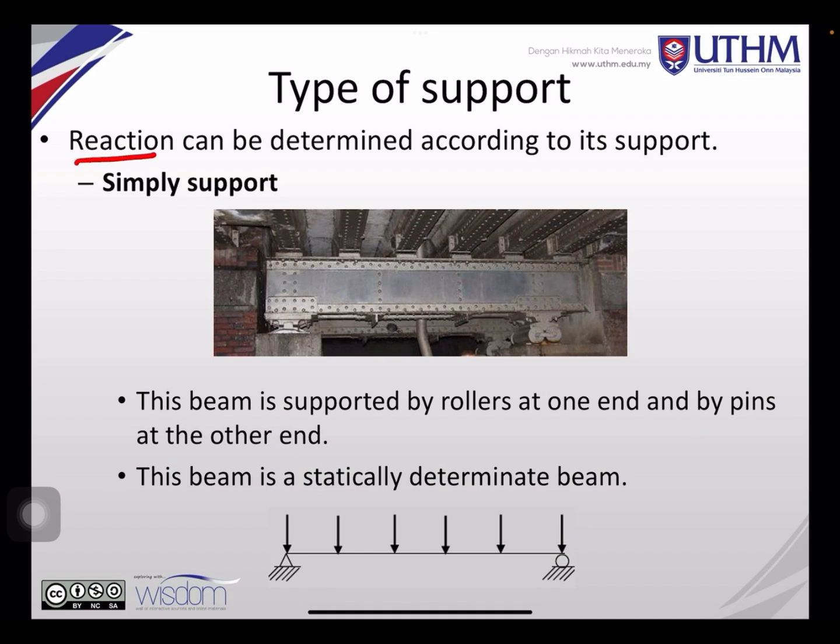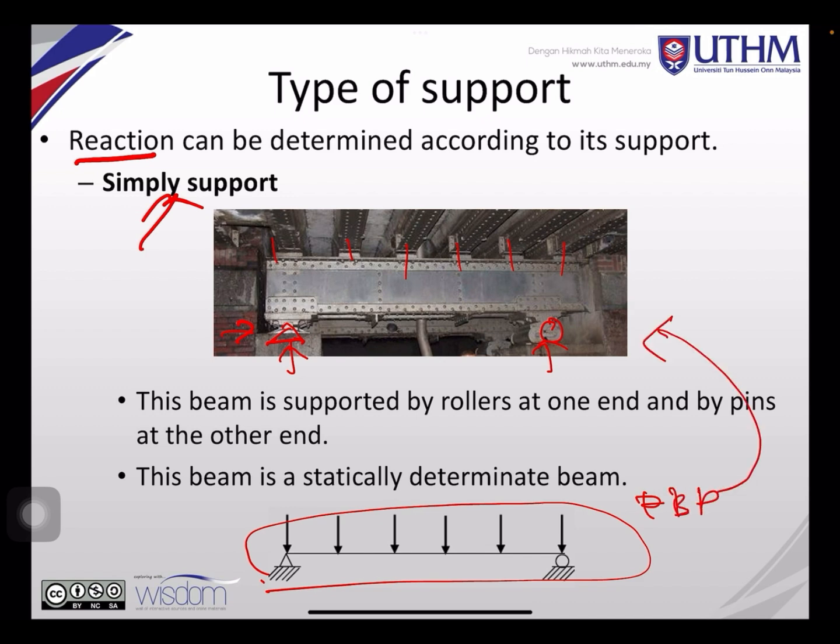Support reaction, the reaction can be determined according to its support. So first, you will always see this is a simple support. This beam, you can see that here is a pin, here is a roller. So this one you have 2 reactions, this one you have 1 reaction. So this is statically determinate, and the load here you can see is applied here, here, here, here, here. You can see, right? So this is the free body diagram for this picture.